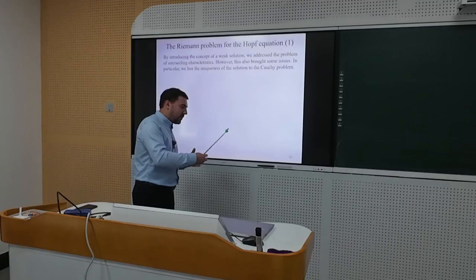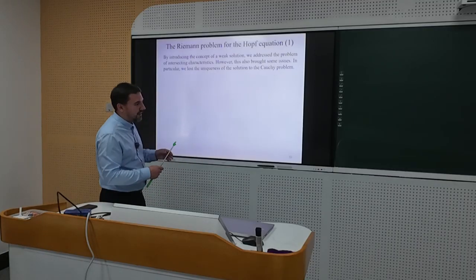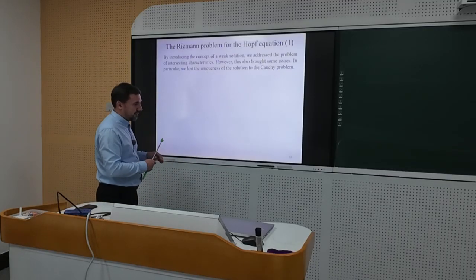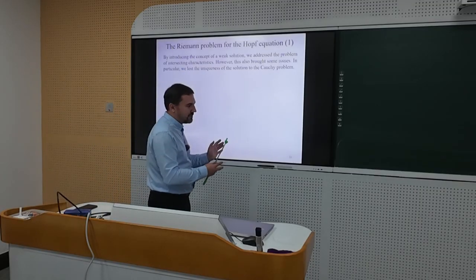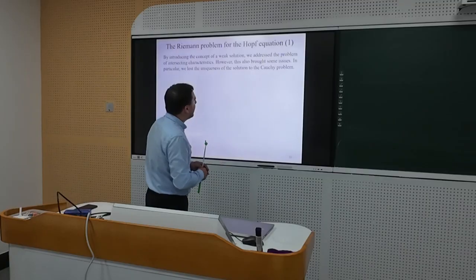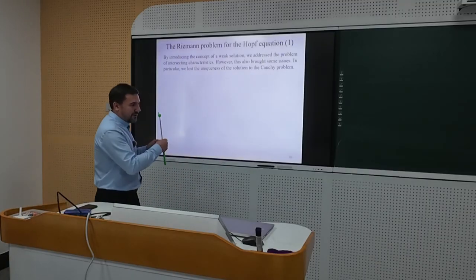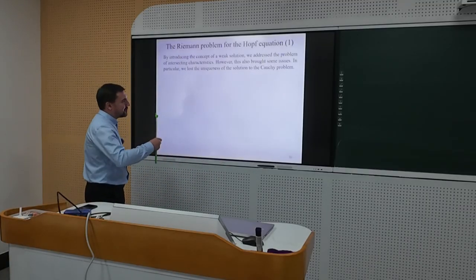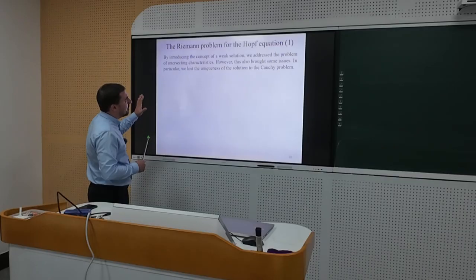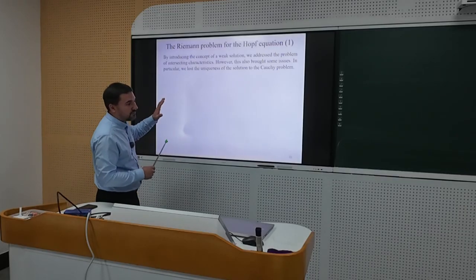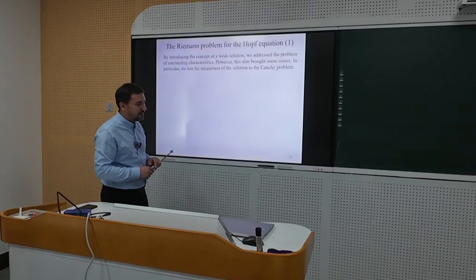So the computation of numerical fluxes in finite volume methods depends on the solution of the Riemann problem for gas dynamics. And the solution of the Riemann problem depends on the knowledge of relationships for shock waves and rarefaction waves. I will try to follow and explain all these logics later. But from a theoretical point of view, we should know how to solve the so-called Riemann problem for hyperbolic problems.